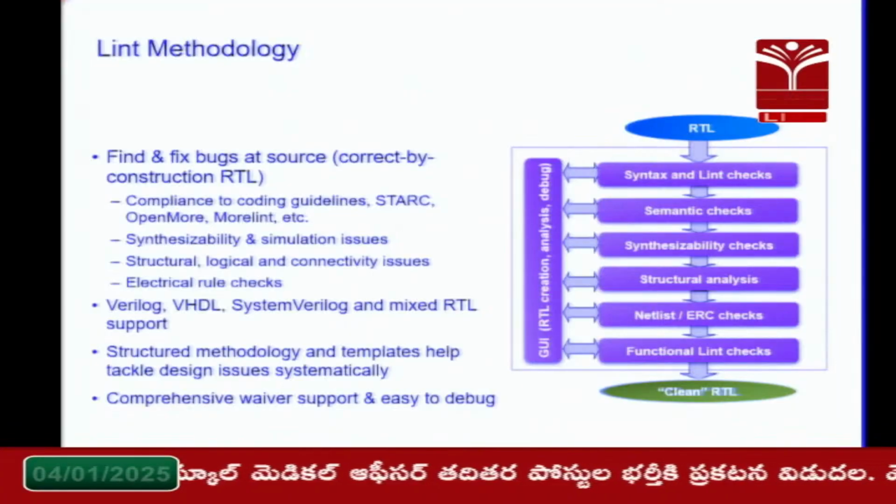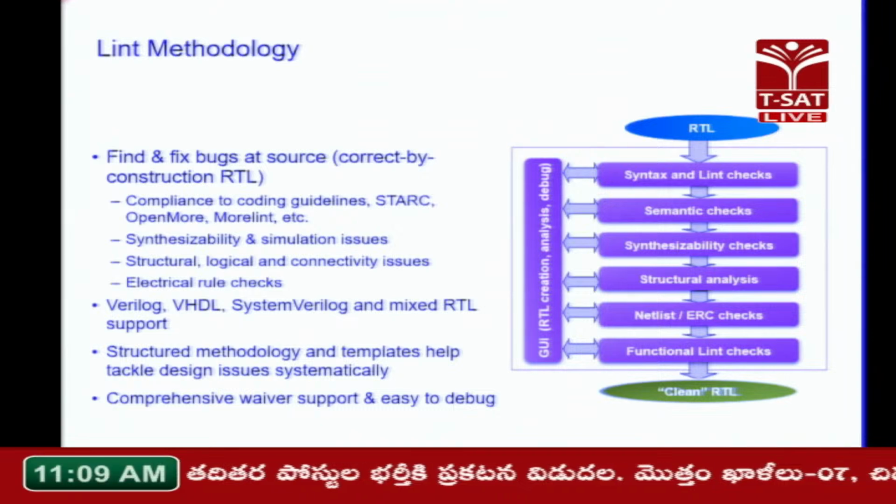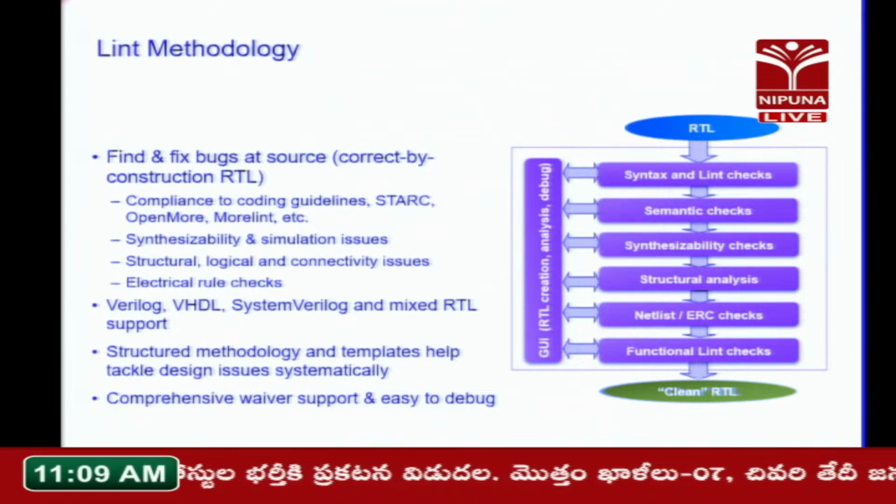So if you have to ensure your design is clean, you can perform the lint checking, which can help you to understand if the constructs are legal constructs, are synthesizable constructs, are structurally good or not, and then we can ensure my RTL is clean right up front, so that I can take it to the next steps. That's the lint methodology. Okay, let's take a call here.